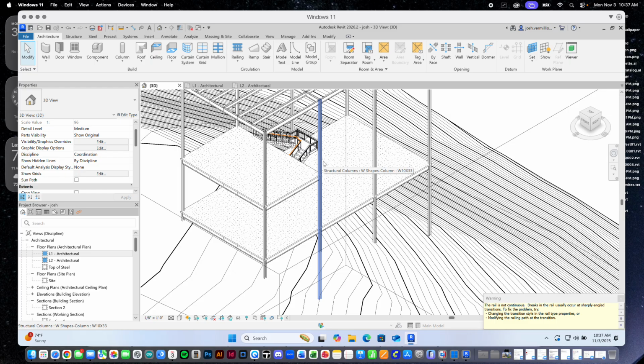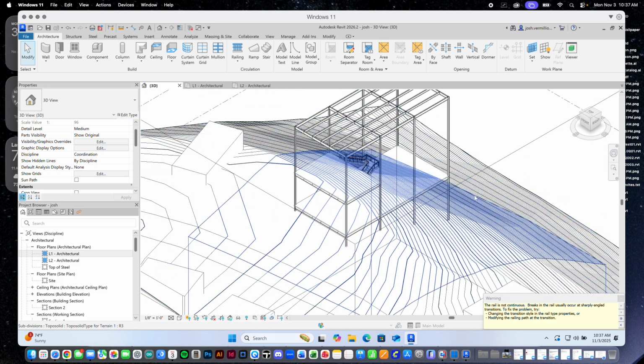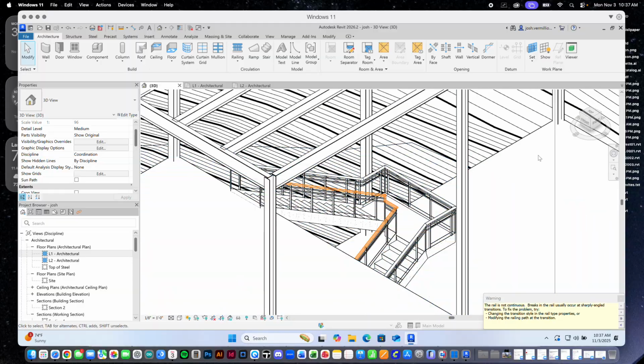I mean, Revit has the kit of parts. They're right there, right? So, you need to make stairs, you need to figure out what the size of your stair towers are going to be for egress, you need to size your cores, etc., right? All those big decisions you make at the beginning of a project, you can do that here. Once you start to establish your floor to floors, you can begin to understand exactly what size these things are going to be fairly quickly, right? And in an automated way, generate them, and they'll show up on all the plans and sections and everything else.